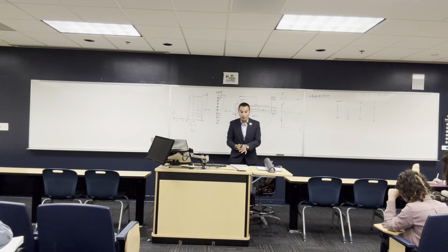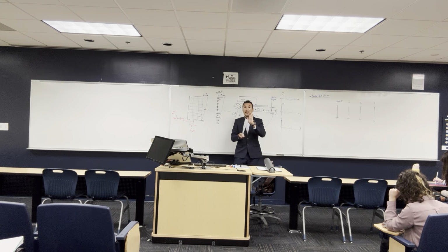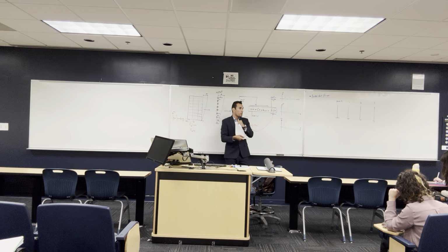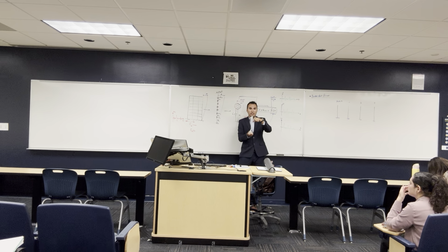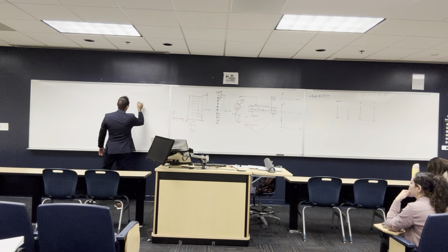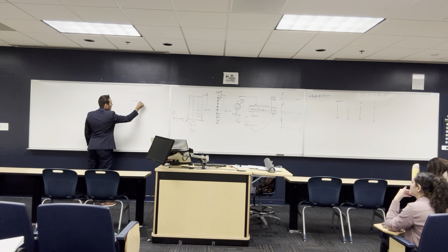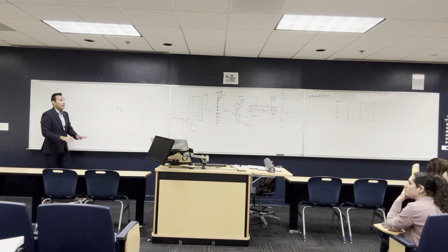And by the way, buildings sometimes have a torsional mode. They can twist. It depends how easy it gets to this mode. Sometimes a building doesn't start with this mode. Actually, it wants to start with this mode, but there's something in the stiffness that makes it twist. How? Let's say that you have a building like this, all right? And there's a force F base coming from an earthquake that is gonna hit this building.